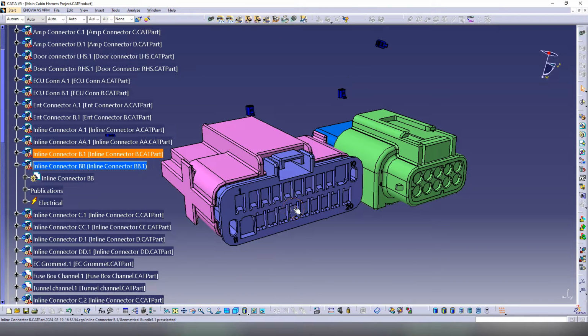The only way you will design a connector is if the supplier tells you, look, I do not have a CAD model for that connector, it's old or whatever, we lost it, and you have a drawing left somewhere from the connector. Let's say you can use that drawing and you draw something that has fewer details. But let's say also if you do not have the drawing, you need to get that connector in hand. You need to measure it with a caliper or with a ruler. You need to measure it very well and then design the connector with fewer details. This is the only case where you do that.